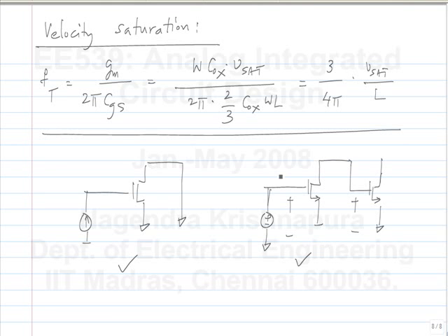It's something that is related to the intrinsic behavior of a MOS transistor. So, generally higher FT means that you can make circuits at a higher speed, but this is measured for a single device. So, that limitation you have to keep in mind. It does not mean that if FT is 80 gigahertz, you can make 80 gigahertz amplifiers using this technology.